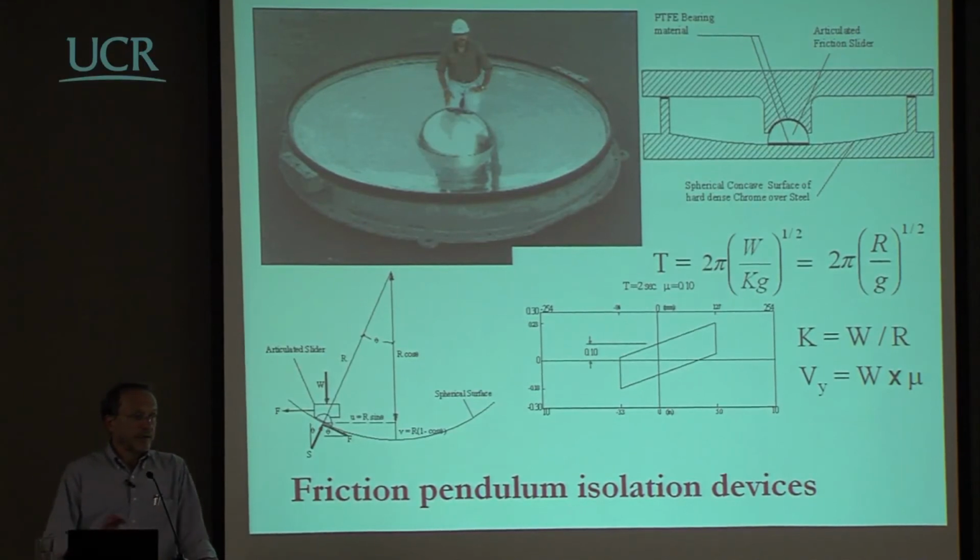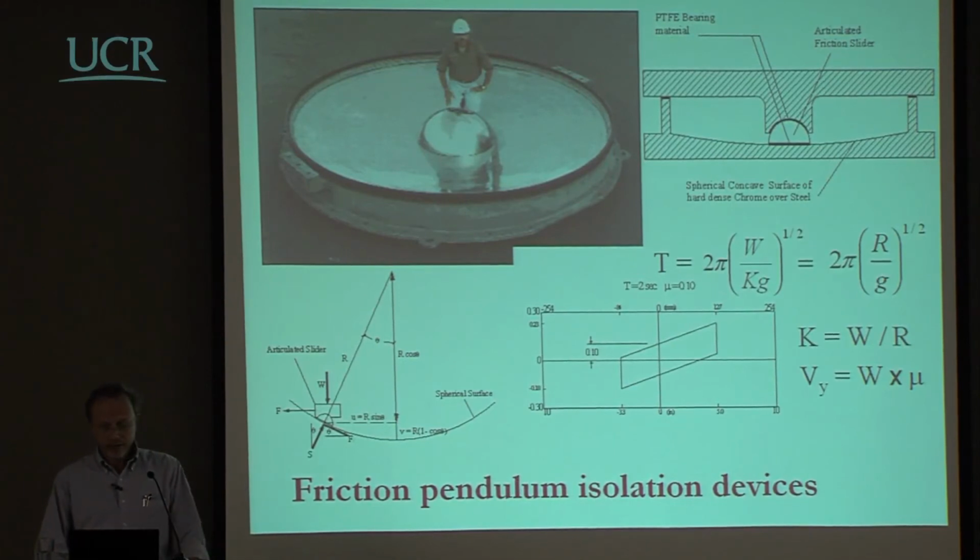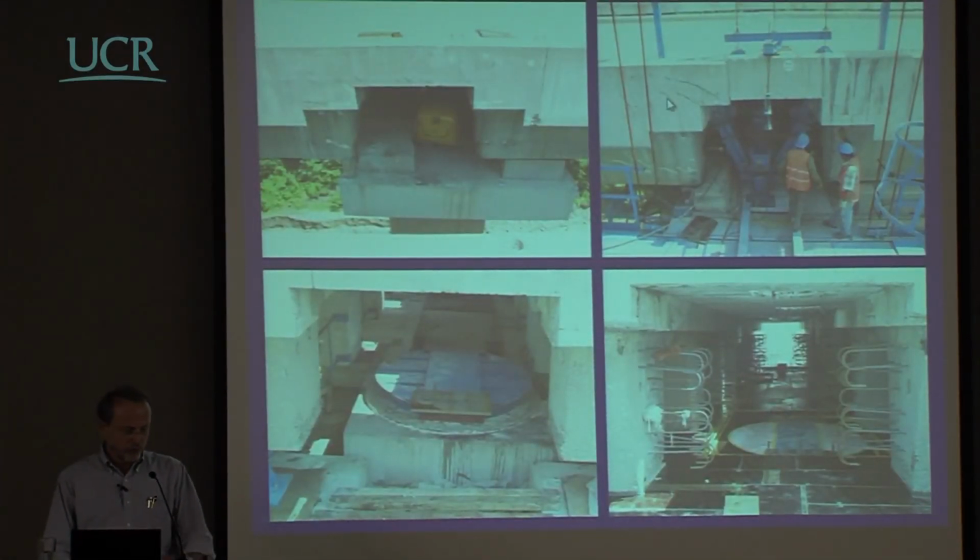And this again is something that I'll discuss tomorrow when we will talk of base isolation, or isolation as a whole. And this is just to conclude this, and I have only one last example to show you. This is just to show you that here there is some demolition of the internal part of the energy dissipating unit. Here we are moving the deck up and then transversally and longitudinally. This is one of the new friction pendulum devices.